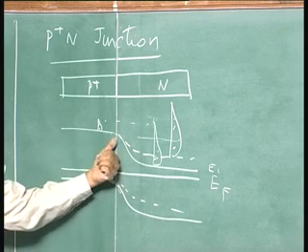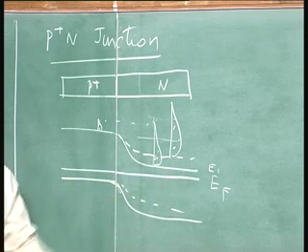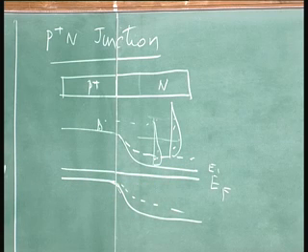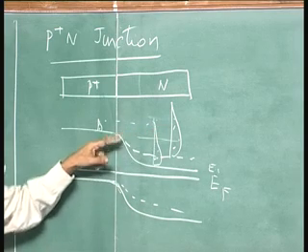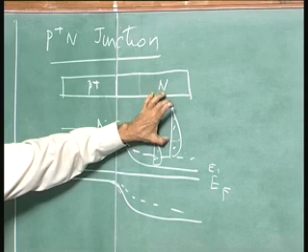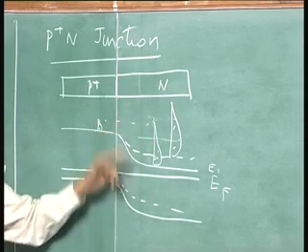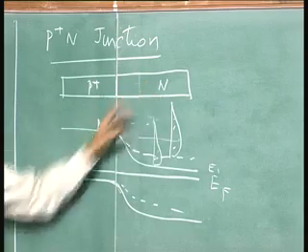at the surface here. You can compute what is the electron concentration on the surface, N0 e to the power of (Vbi minus V) by Vt. That is the concentration here. That is what you are doing, computing how many have got the energy above that. Now, all of them are capable of crossing this barrier, that extra.